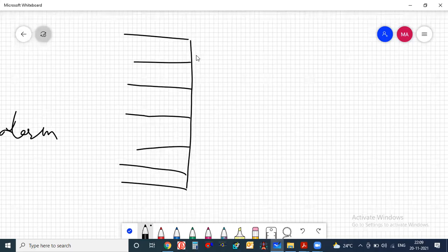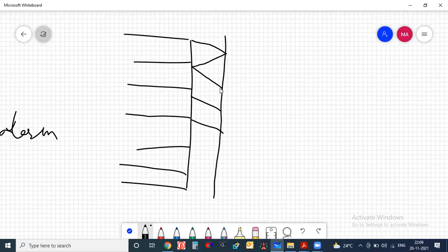And we are maintaining stairwell pressurization in this area. For example, this is our stair, something like this suppose. You can also connect like this, zigzag manner. So I want this area to be protected, for example. So here what we are doing, simply we are maintaining the positive pressure here and negative pressure here.